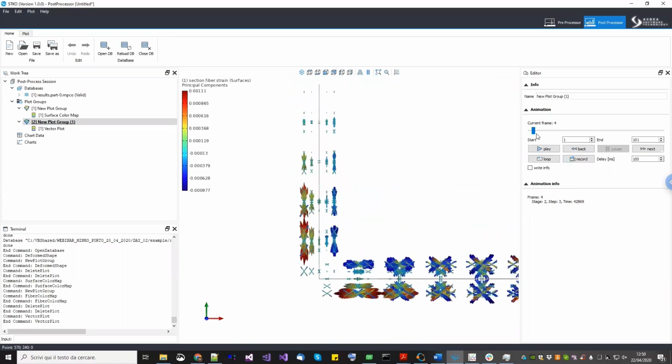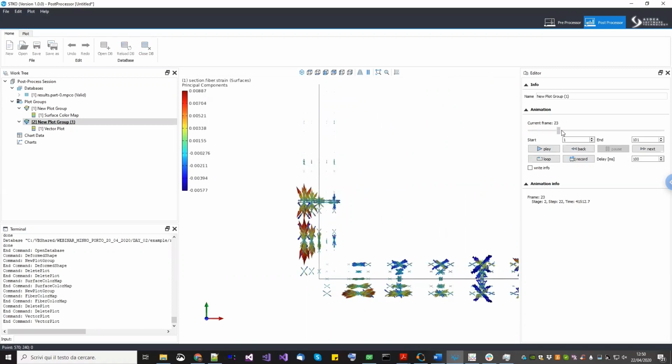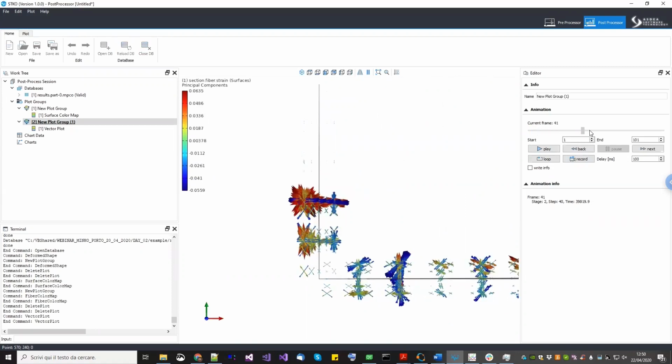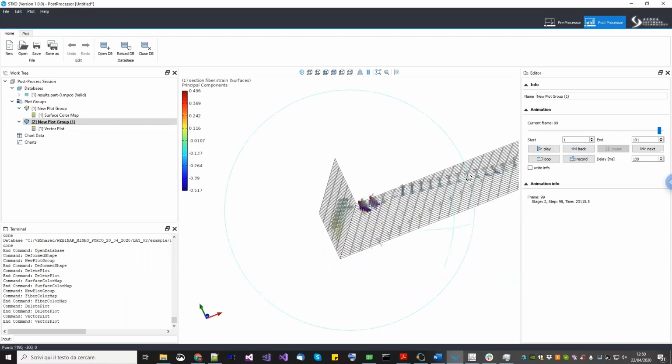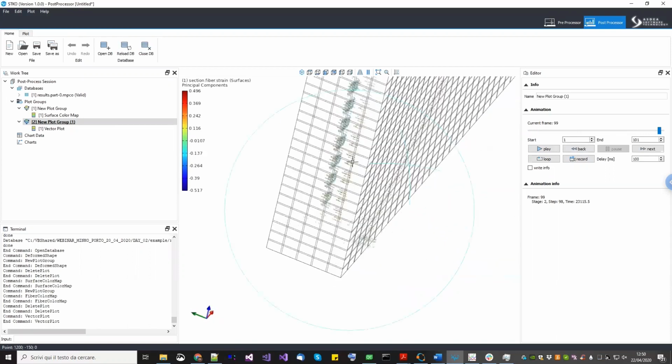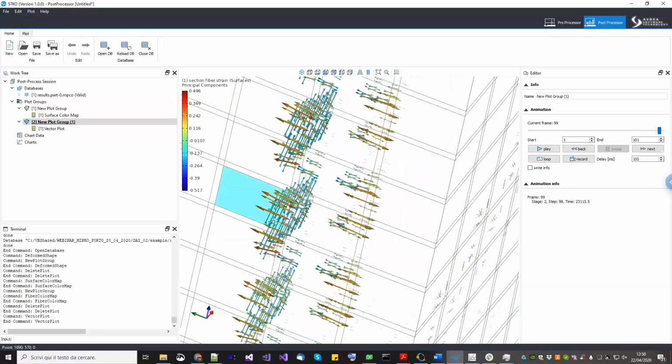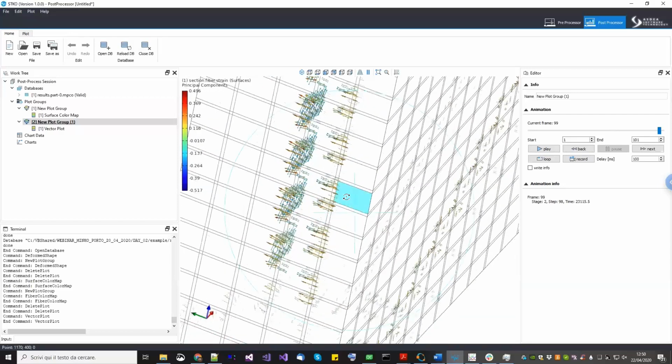And then when we go ahead, we see that the predominant deformation is the transverse shear, as you can see here. Okay, so this is telling you that when you do this kind of micromodeling, what is actually very important is the treatment of a nonlinear transverse shear.